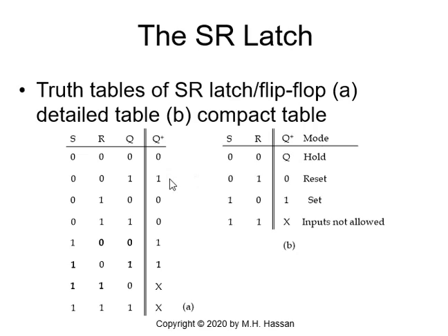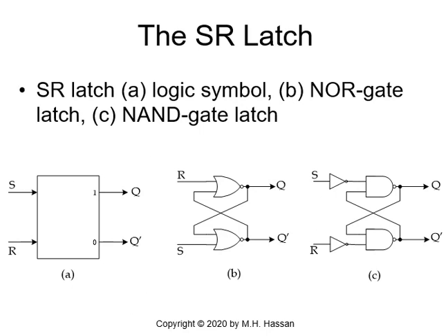We are coming to this soon. To understand how we derive this table, which is extremely important, SRQ, we should understand the NOR gate. The NOR gate, which is the complement of the OR gate, will give me 1 when both inputs are zeros, and 0 otherwise. So if we apply 0, 0 to the NOR gate, the output will be 1. If you apply 0, 1, 1, 0, or 1, 1, the output of the NOR gate will be 0.